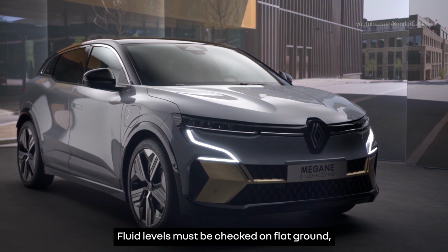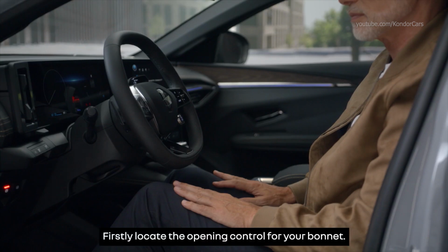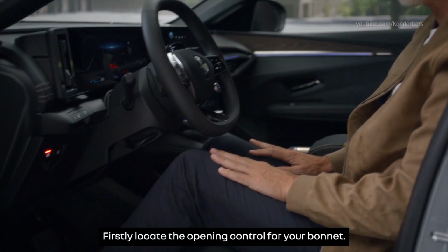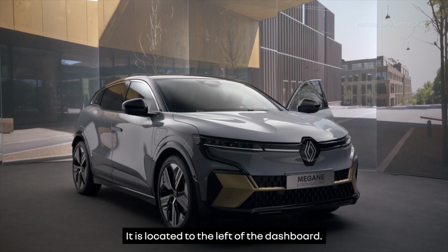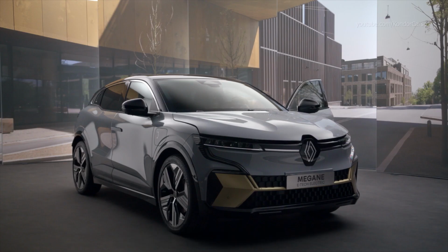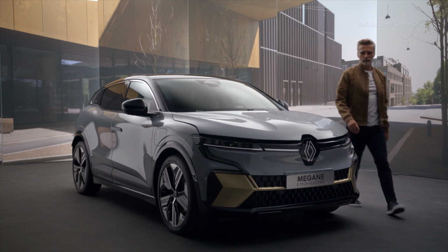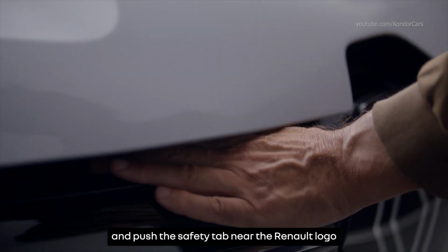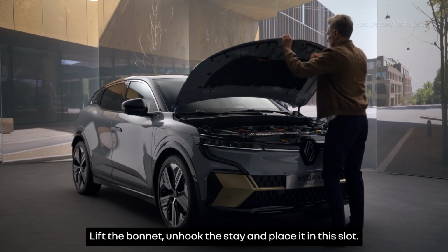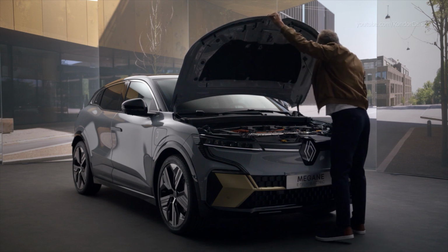Fluid levels must be checked on flat ground with the engine off and cold. Firstly, locate the opening control for your bonnet. It's located to the left of the dashboard. Get out of your vehicle. Lift the bonnet slightly and push the safety tab near the Renault logo to release the bonnet. Lift the bonnet, unhook the stay and place it in this slot.